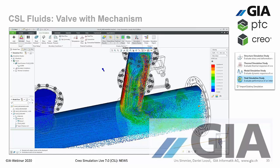Yesterday I was surprised because I was installing Creo 7 on my old computer, and there with a 4 years old graphic card, Quadro M1000M or something like that, I was also able to analyze all this stuff here. Really the need of having a very, very good and expensive graphic card is not here anymore because Ansys also changed, let's say, the solver and now much more graphics cards, the most of them, of course, NVIDIA, are supported right now.